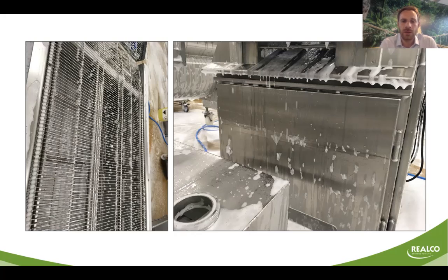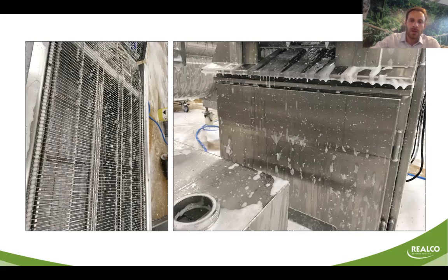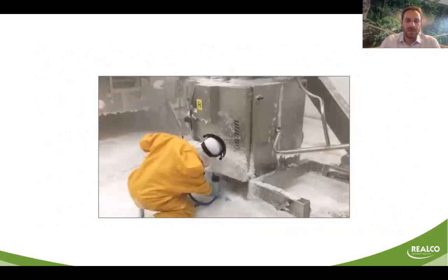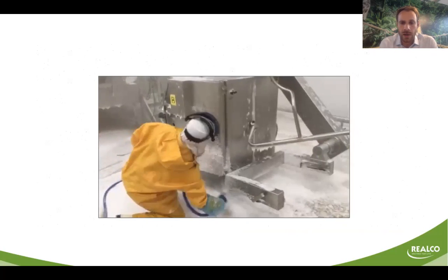So you have the foam here that has been applied, and as you can see, the foam is not in good condition, so the foam will not stick to the surfaces during the time, again, the contact time. You don't have the time of contact, and so you cannot have a good cleaning or a good sanitation. In this case, you have a good quality of foam, so you see that the concentration is reached, and so you will also reach the time of contact. That's why it's important to control that kind of equipment to be sure that you are able to get what you wanted. Here is just a quick video of a guy applying the foam.